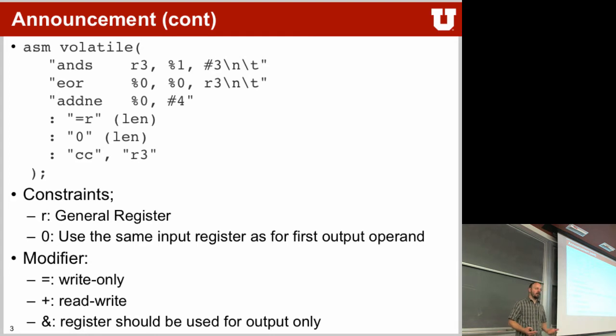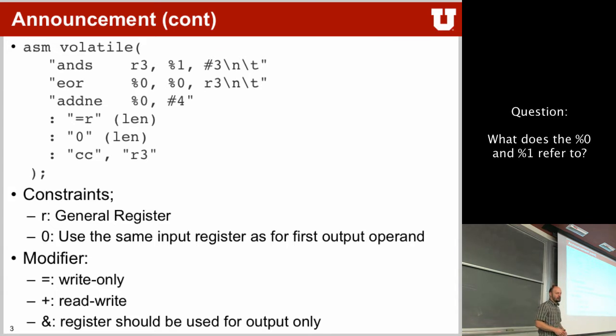Sometimes you also know that your microcontroller can do specific multiplication instructions or optimized floating point instructions. Sometimes you have to go down into assembly to actually make use of these kinds of functions because GCC is unaware of them and can't optimize your C code in order to take advantage of these kinds of things.